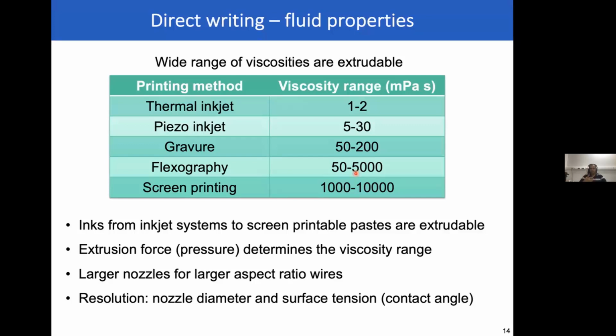So that's why we go for the composites. So that's probably my suggestion, to see either if we have some composites, or to see whether there are any surfactant layers that you can actually deposit on the zinc oxide before you coat the silver nanowire. Again, it's going to depend a bit on what sort of application you are looking at, because you said you have zinc oxide on both sides.